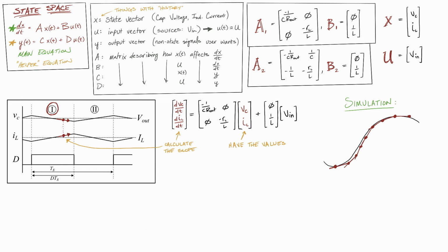Now, let's assume that I decrease the step size. It's basically the sample time, okay? You start at the exact same point with the exact same slope, but the next guess is closer to the previous point. Now you see how much closer the calculated line is to the actual value. This is how simulators work. Basically what you're doing is linearizing around an operating point, moving forward some small time step, and then linearizing around that one and moving forward again. So it's powerful because it's how simulators work.